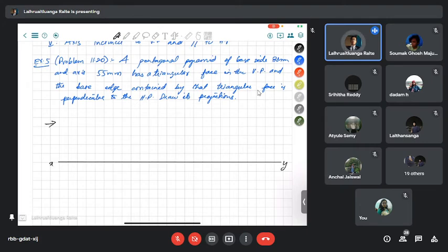so in our first stage, we are going to have one of the triangular faces with a base as a line, as an edge. So we are going to make that edge on the right hand side, and we are going to make that edge, as per the question, perpendicular to the HP.